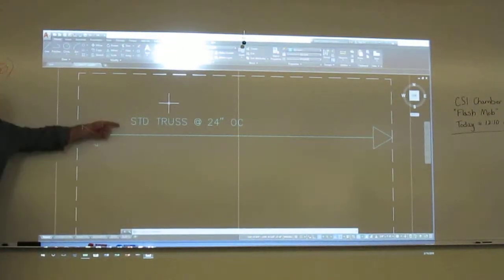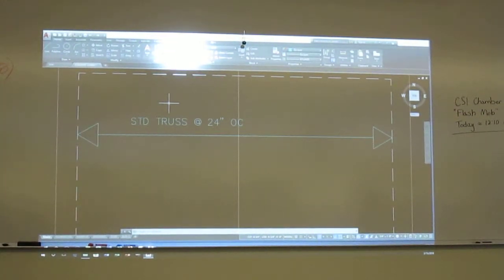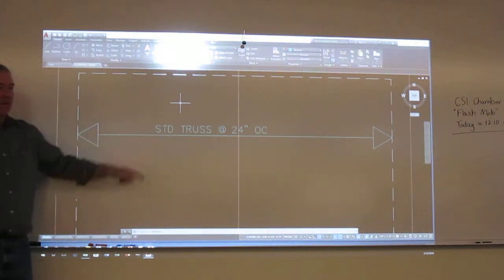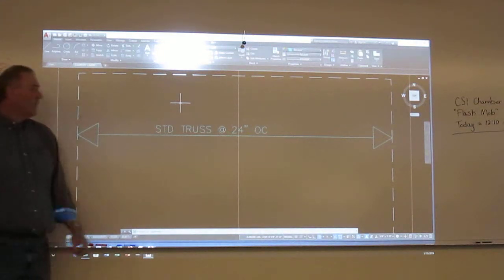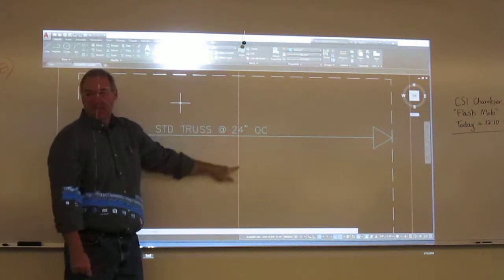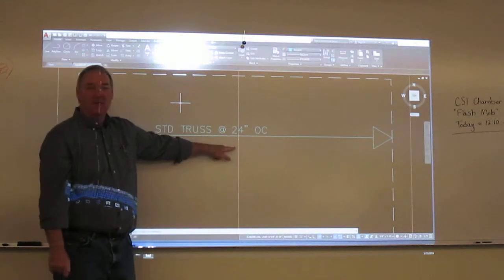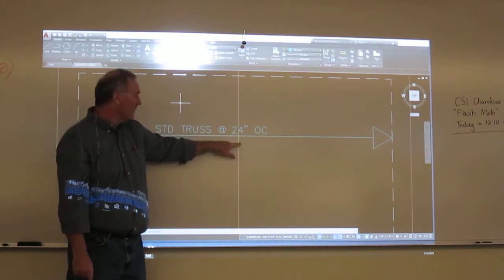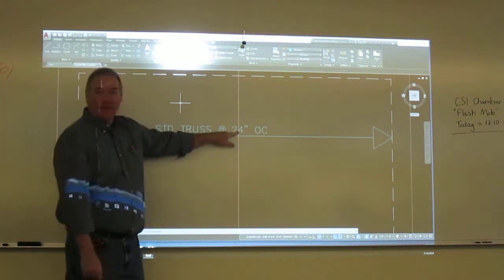So you're just going to take this thing and lay it right alongside the line, make sure it doesn't get too close to that line so it reads well. Okay, so I'll just come in and do a move and set it somewhere. Now, if I'm forced to put it here, folks, use your board drawing skills. What's the problem with where I've got this? What's the line weight of this? It's my roof peak. It's .031. That's a very thick line. Okay, so somebody's not going to be able to read that.